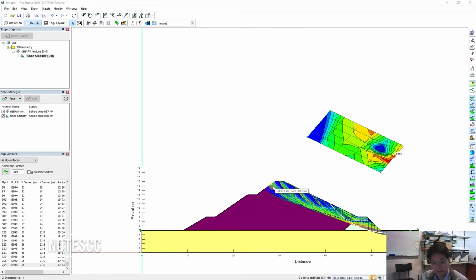Before I finish this tutorial, I just want to emphasize again that this is just a simple tutorial. There are a lot of mistakes in that one, so please do not copy it for your design. For example, the slope of the dam inside the reservoir must be milder than the slope at the downstream side because it has the saturated part over here, so therefore it has uplift force, and therefore the soil block slides down more easily, and it doesn't have a strong drainage over here to support at the toe, so therefore the slope here must be milder than the one at the downstream side.